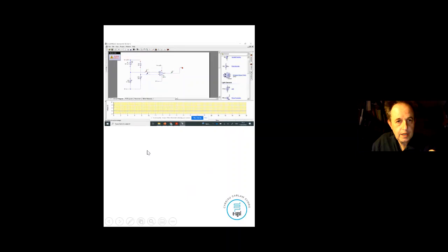What they do is I have two resistors, 1 and 2, they're fixed, right? And those fixed resistors will keep that voltage there at an exact point. Now in this case, I've got two resistors, 10Ks, they're exactly the same. So if they're exactly the same, they will have half the voltage of the supply. So that point there is fixed at 4.5. You can change it if you wanted, put a variable resistor in, if you wanted to change the threshold values. And this is what I've got here, is